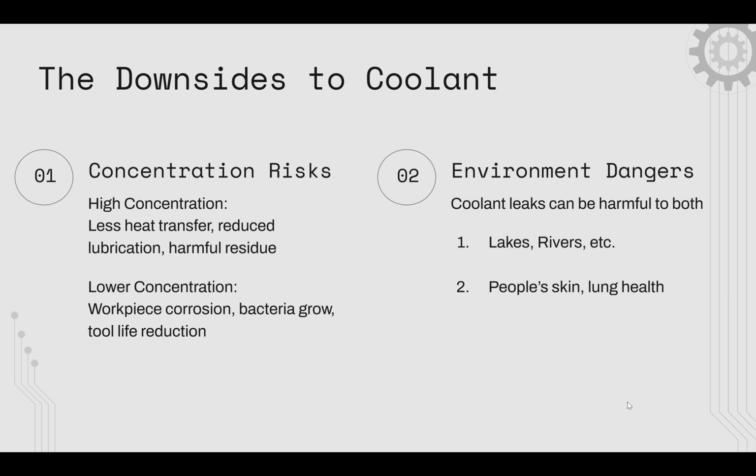While coolant is beneficial to part finish and tool life, it is also dangerous. If coolant is not at the right concentration, there can be risk of less heat transfer and increased corrosion. High concentration also reduces lubrication, which removes the clean surface finish desired. Lower concentration corrodes the workpiece and can also reduce tool life.